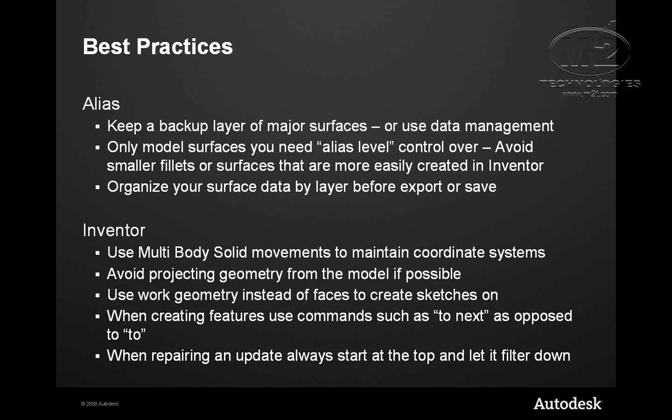And then, of course, using commands such as "To Next" as opposed to selecting a surface will go a long way. And then if you do have a model that blows up or you run into a bad situation, always repair from the top and let it filter down. So the features that are below always reference features that are above. So you always want to start at the root of the problem and let it filter down.